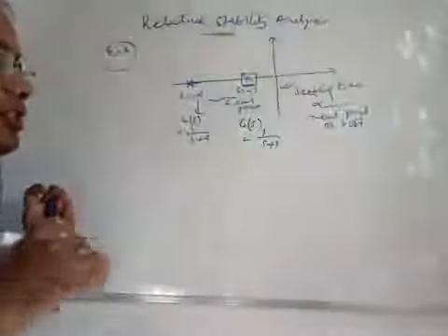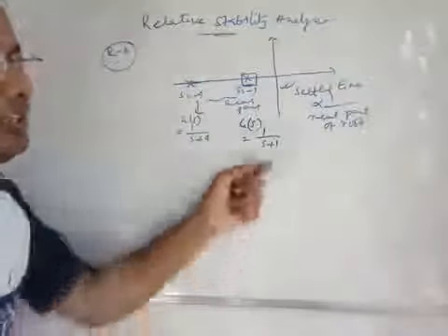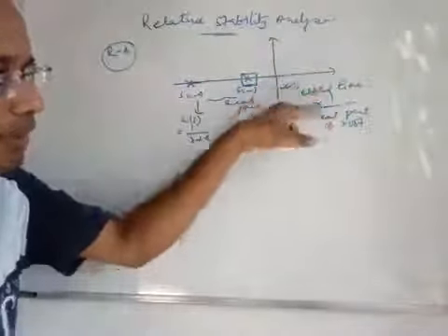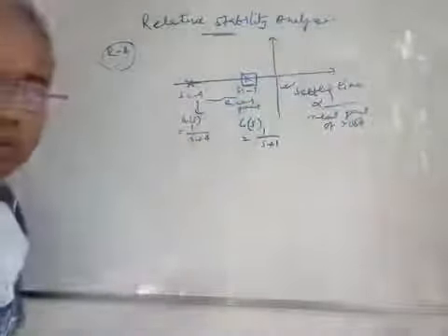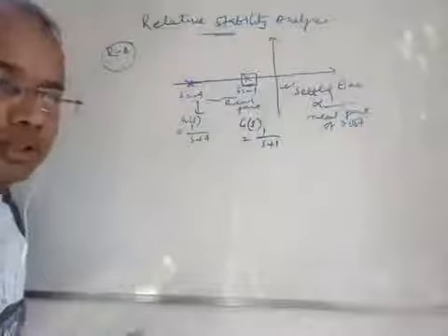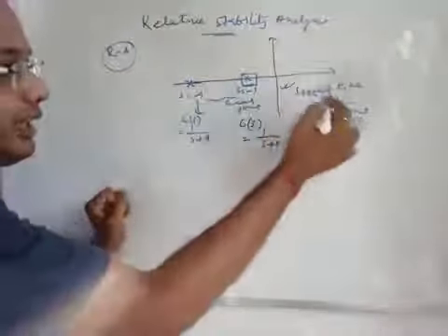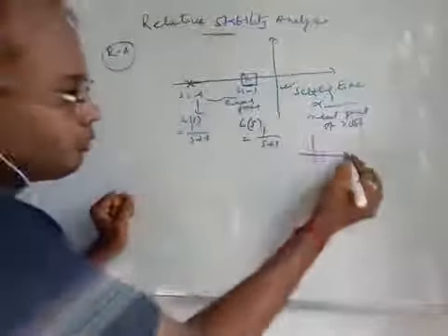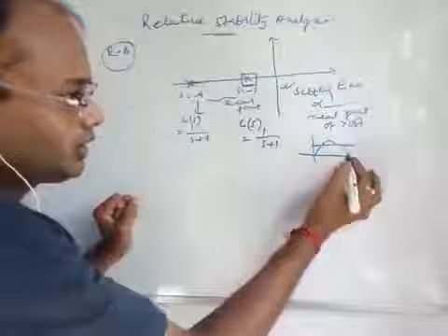From the time domain analysis, we know what settling time is, and we know the settling time is inversely proportional to the real part of the root, or the real part of the pole positions, considering simple root conditions. Settling time means how fast the response will settle to its desired level.